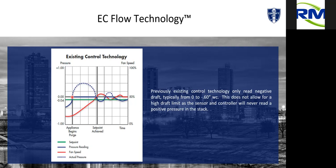That speedometer just stopped. It didn't mean you weren't going any faster. It just meant that it couldn't handle it any longer. So just because we stop at 0 doesn't mean that pressure isn't continuing to rise. So the computer in the controller says, well, we're only 0.04 of an inch away. We're going to slowly ramp that fan up until we can get to set point. And eventually it will taper off and we'll get there.